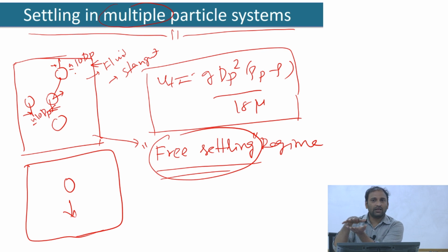That means if I am working with a 10 micrometer particle in a fluid between two plates for rheological measurements, the distance between the plates has to be at least about 10 times the particle diameter. In that case, I would maintain a gap of more than 100 micrometers, because the particle size is 10 micrometers.